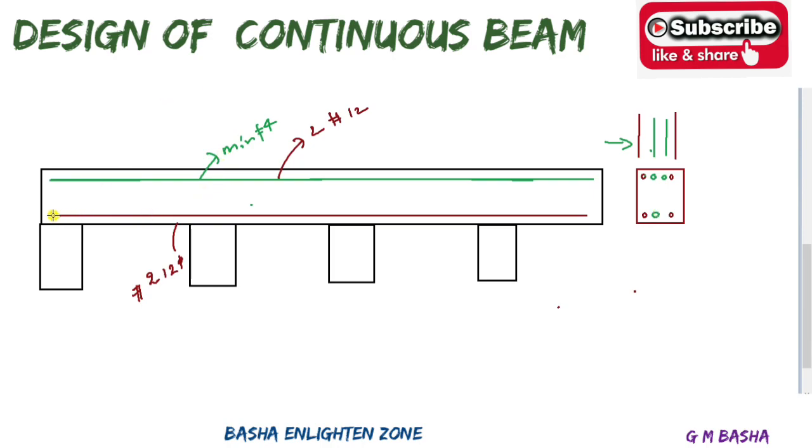So you can keep one straight bar from here to here. So if you see here, one bar we already kept like this, another bar will be kept like this, and if I keep one more bar here, so if I stretch this bar, these are the straight bars. Sorry, this was in green color, 2 bars already provided, one more bar I will provide like this. So you see here 2 brown bars and 1 bar in green color, totally 3 bars. What they are asking is 3 bars of 12 dia at the mid spans. So it will meet the requirements.